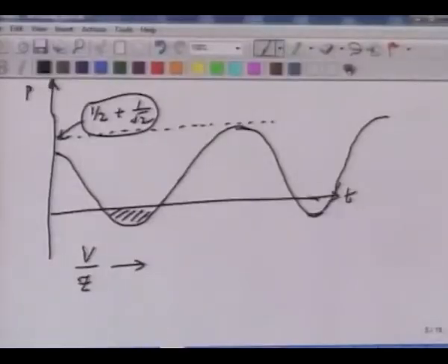So it draws more current, which means the heat dissipated in the transmission lines goes up. So basically the overall efficiency of the system goes down. So what people do is they try to rectify this by putting some capacitive load in parallel to the inductor, and that kills the influence of the inductive load so that the current comes back to the original number.